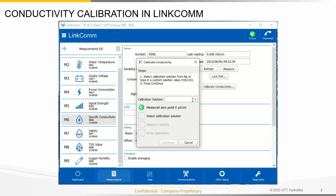Next, it will prompt you to select a calibration solution for which you want to calibrate. I'm going to use 0.5 millisiemens per centimeter, but you can also type in a custom solution if yours is not in the dropdown. It will then prompt you to fill the calibration container you're going to use and put the sensor into the calibration solution. Once you're ready, hit continue. It will first measure the temperature, wait for that to stabilize, and then measure the conductivity, allowing that to stabilize as well. So we'll give it a few seconds here as it takes its time to complete that.